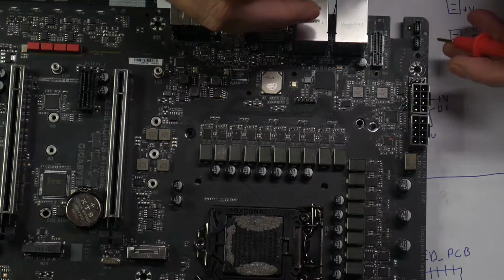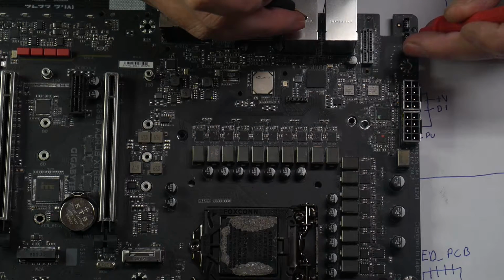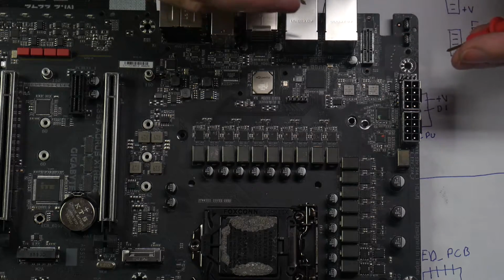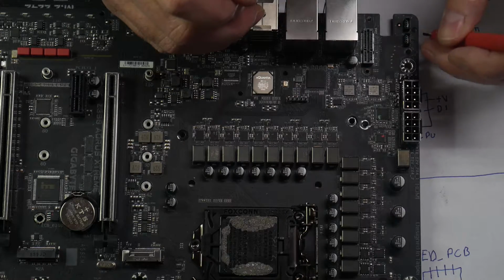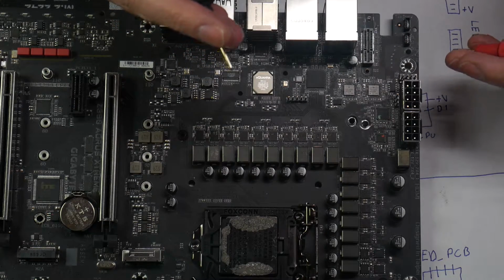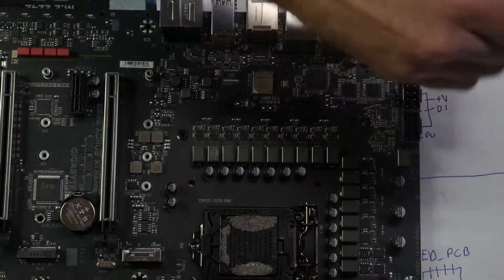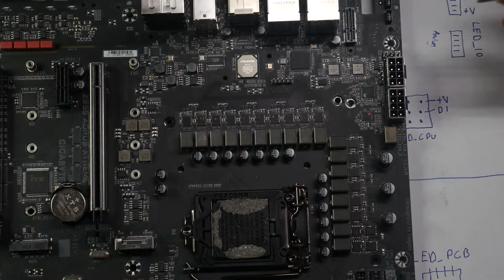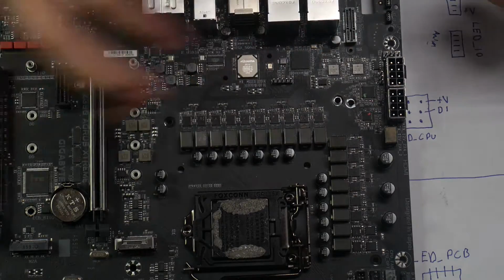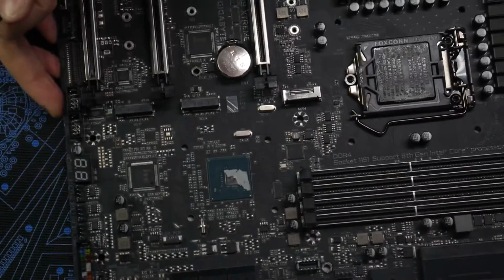So next thing we're going to check is this next little header right here. Okay, there's no continuity right there. And so if we're not showing continuity on ground, if we're not showing continuity anywhere on a header, and it's for LEDs, then we have a good indication that that's going to be analog. So this one is going to be analog. The other ones that I've checked so far are digital, which I'm not surprised, because if you watch any videos on a motherboard, you'll see the addressable effects that are going on. So we'll come back to that one.